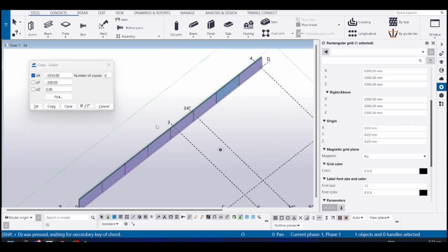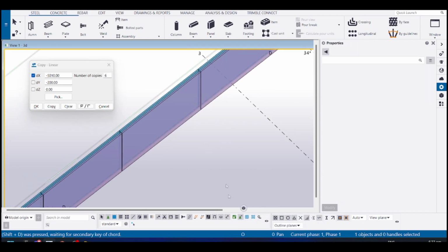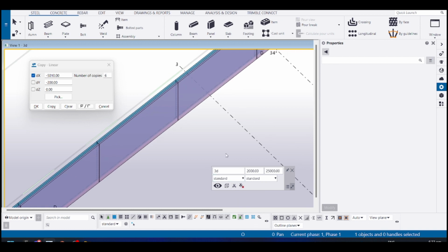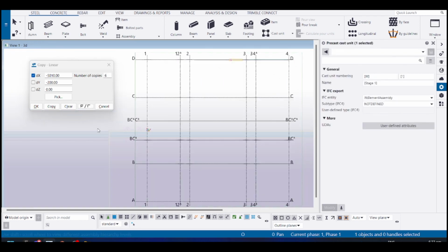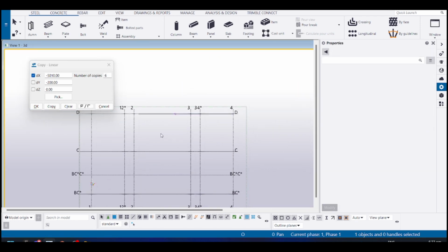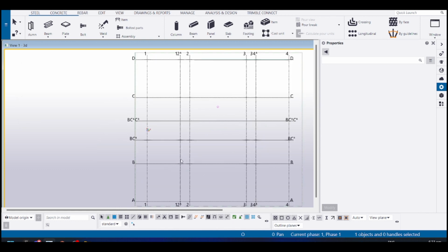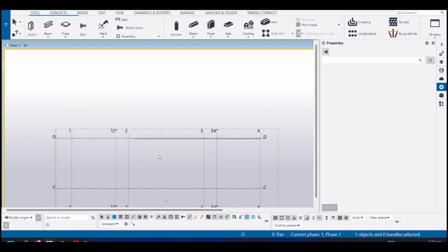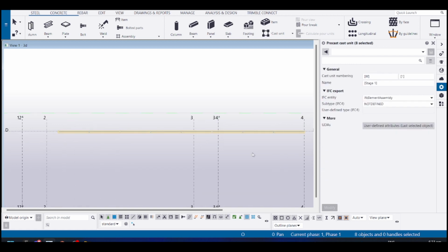So these are twin walls, and I can just turn on the assembly selection mode. The reason I told you this is a bit of an annoyance is that sometimes when you want to select something, this will pop up in the middle. So you want to just hit K and it will disappear. With this button again, you can select this now. So this is a twin wall that we've drawn over here, and you can then select these twin walls individually as you want them to be selected.